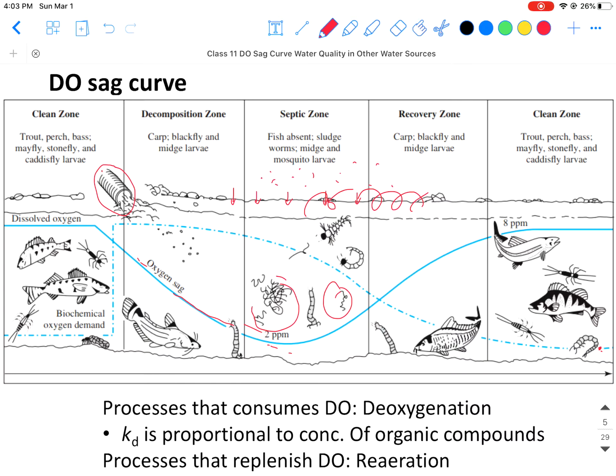And as we consume all of these organics that are being emitted into the river, the oxygen concentration can go back up again. And of course, not only can oxygen dissolve, but also maybe in the river there are some green plants, right? The plants will also generate oxygen and it can dissolve into the water. So as the dissolved oxygen concentration increases, all of these different levels or different forms of organisms will reappear. We're going to have the insects and the fish again.